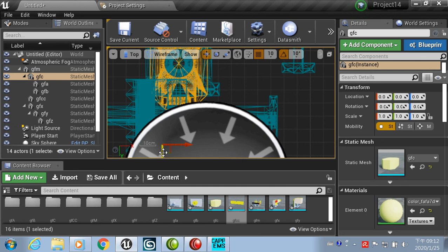Put the cursor on top of the yellow arrow and press the middle button of the mouse, and at the same time press the ALT key, to put the center of the arrow to the center of the pivot point. This is across the positions because the tool has the constraint.